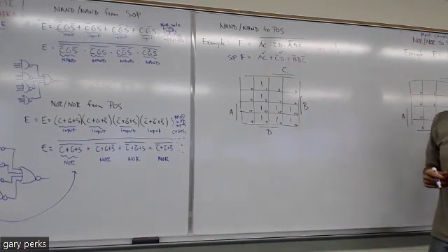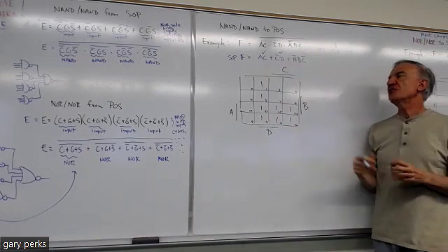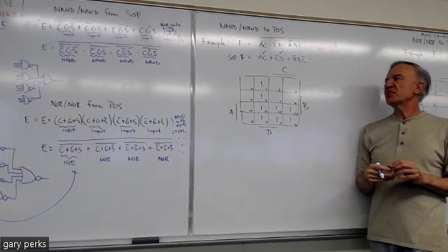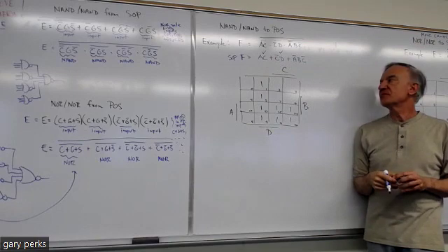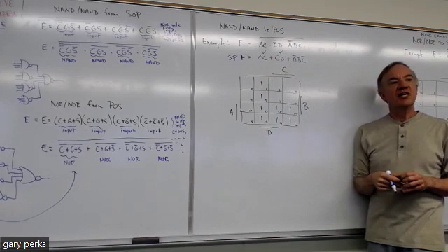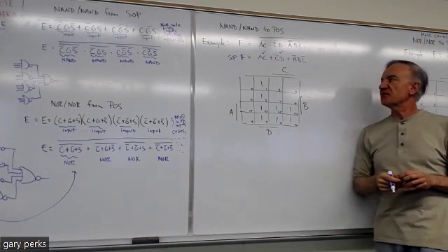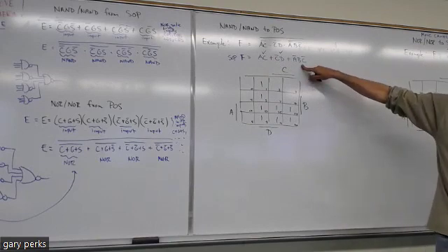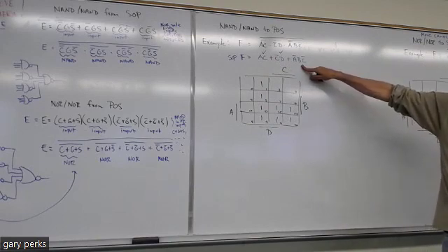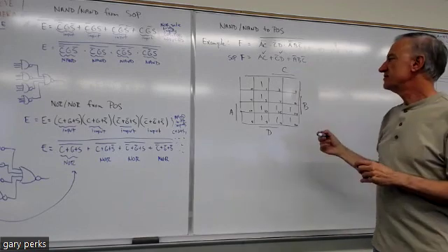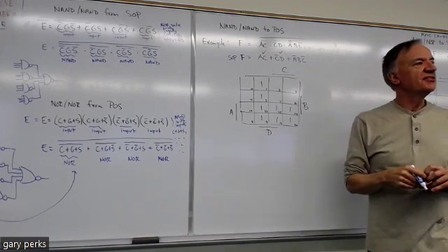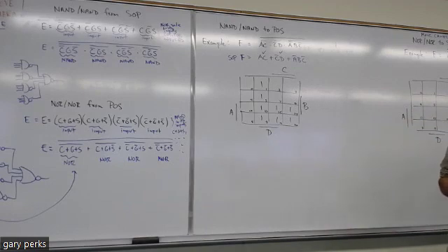Now we have not A, B, not C. First of all, what number grouping is that? Since it's a three variable term in a 16 cell map, it's a 2 grouping. So which two cells would give us not A, B, not C? 6 and 7? 4 and 5? 4 and 8?